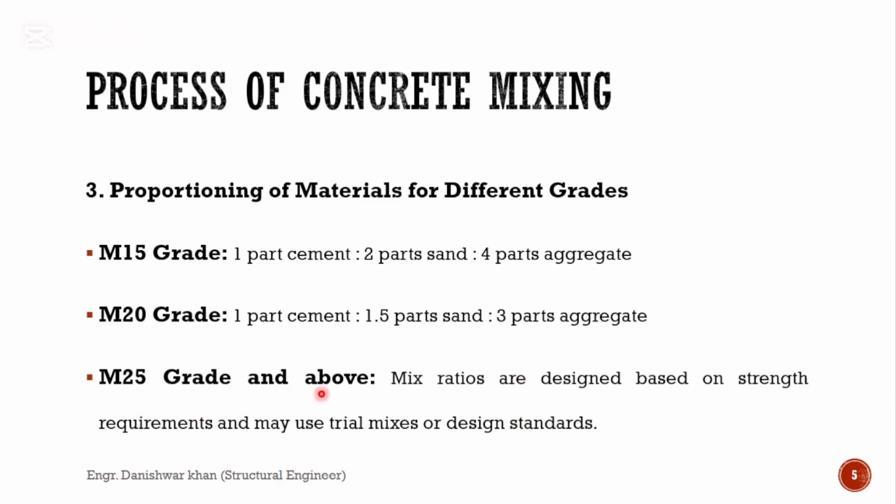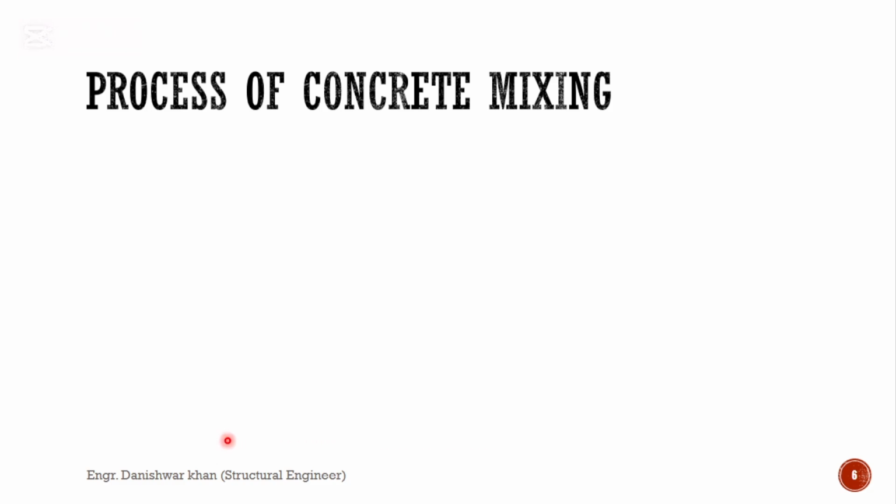And for M25 grade or above, mix ratios are designed based on strength requirements and may use trial mixes or design standards. Choosing the right proportion is critical for achieving the required compressive strength.